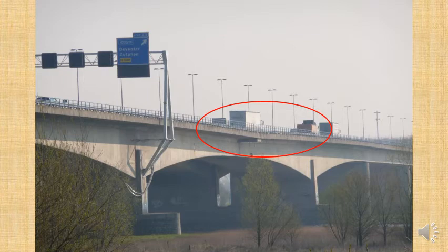And it's an undesirable thing because, first off, it's unsightly, but potentially if you had too much creep, those bridge beams wouldn't sit next to one another and you would end up with a big hole in the bridge. So it's a very common issue with bridge beams, but it's also a big issue with buildings.